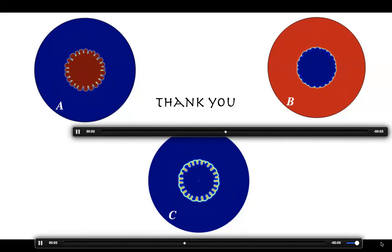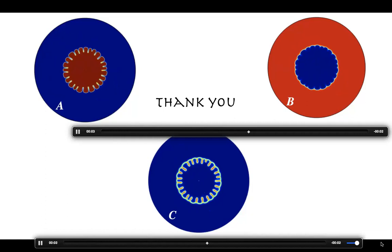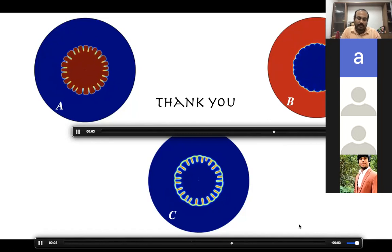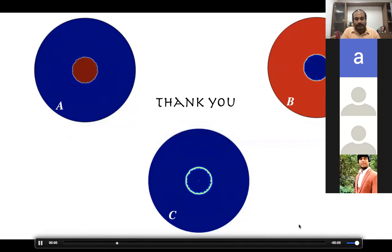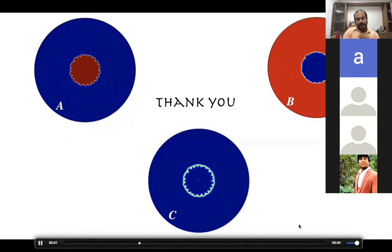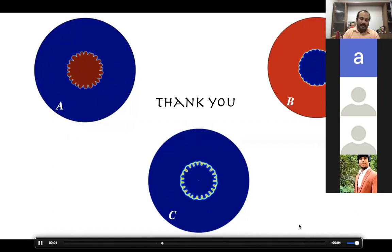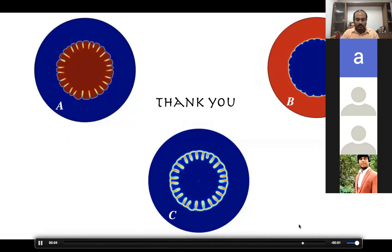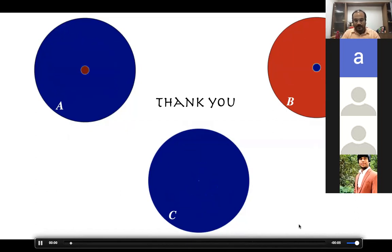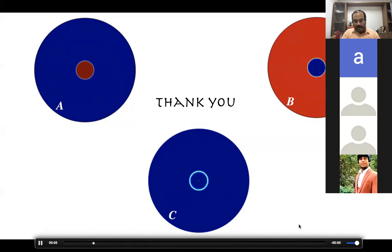Yeah, I'm Pooja, a PhD scholar from IIT Delhi. So overall, in short, the reason for the stabilization is basically the diffusion, whether the reaction is happening or there is no reaction. The stabilizing mechanism is always due to the diffusion, right? In inviscid flow, yes. Okay, so all the simulations are performed for a finite Damkohler number. As we can see, the stable zone depends on the Damkohler number. It is a function of the Damkohler number.